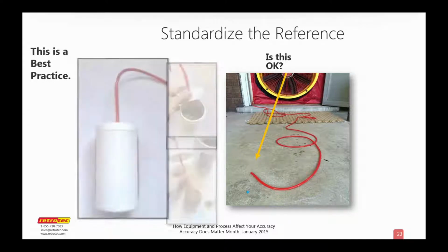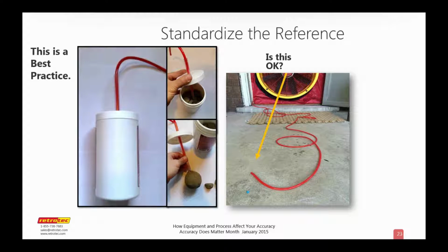Now keep in mind that when we're using any kind of gauge, it's a manometer, and a manometer is always a differential pressure gauge. So that's the difference between 2 points. It's not absolute pressure, it's the difference between 2 points. So if the reference that your input is referenced to is off, then your findings are going to be off. And if one guy has the hose here and the other guy has the hose out exposed to the wind, and we're just doing a specific single point residential test, we can find all kinds of problems with this.